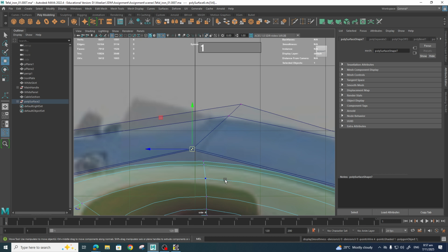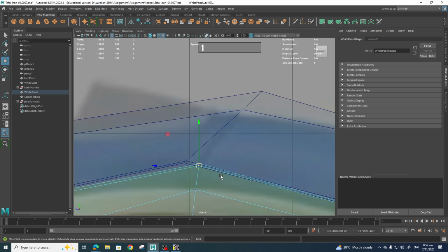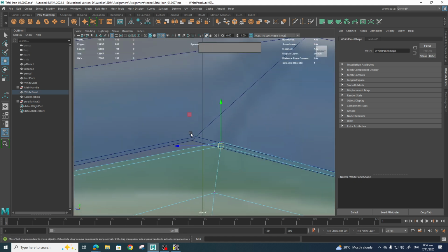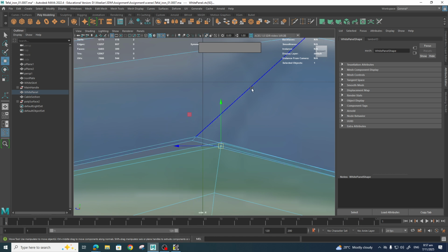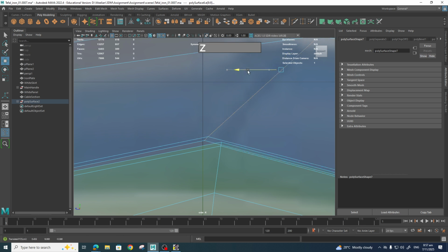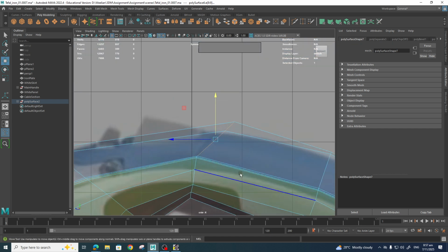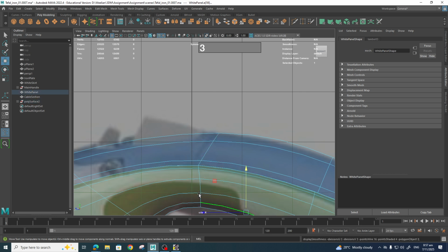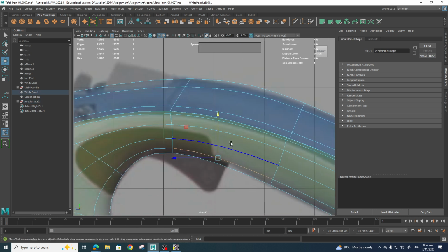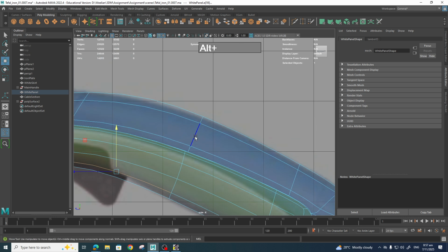Okay, switching all to level 1. In order to make sure that this really matches, I will have to select this edge, move it back, double click to slide this loop, slide it back, and then get it to match this section over here. Let me see whether that, yeah, that's good. Okay, I'm happy with this.